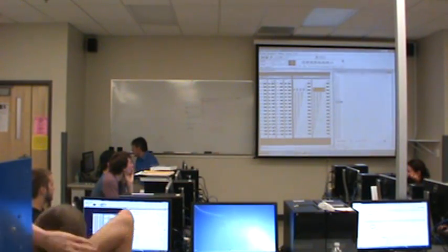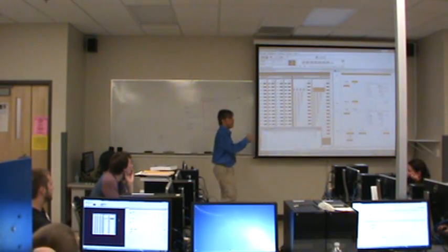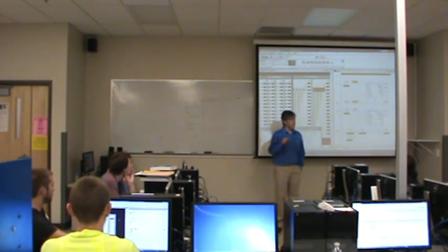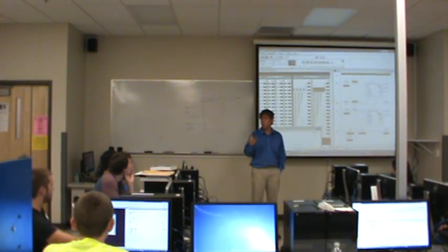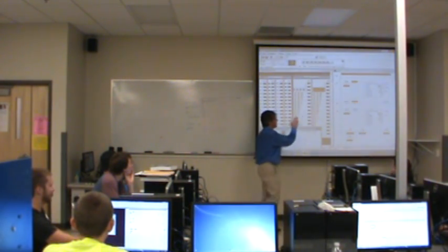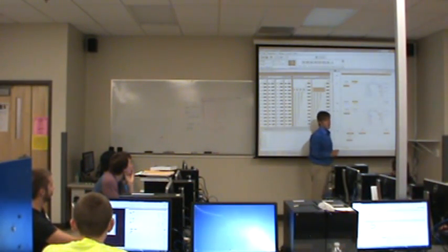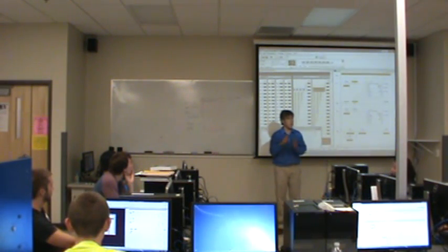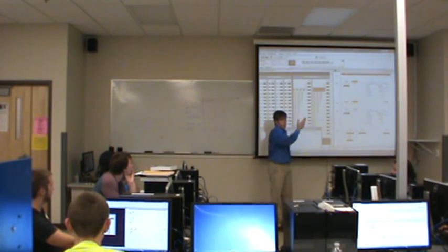Now there's more to this program than just that. I could set it up so that I had a timer running. Remember how we worked in the traffic light simulator? And we used one timer that self-restarted. We compared the value in the accumulation so that we could turn on the lights. Well, we could set up a timer like that and have that timer, when it's done, trigger the sequence output instruction. And we simply move, with whatever that time frequency or time period is, it would set the outputs in sequence. And you'd see 1, 2, 3, 4, all the way up to 8.